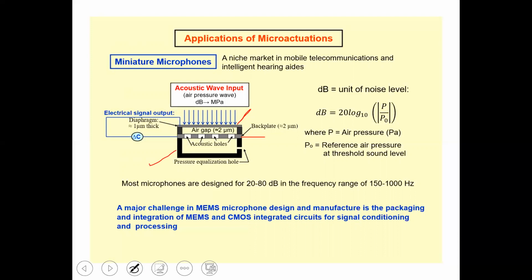So when sound waves come on this diaphragm, it oscillates, so it vibrates. As it vibrates, the air gap between this and this one decreases accordingly, right? When this decreases, air pressure is generated. That air pressure goes through these holes, and when it goes through the holes, a sound effect is produced, right? So this is how this miniature microphone acts, right?